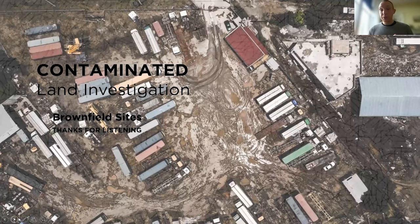So the first thing that we'll do during the phase 1 report is identify potential sources in the area. So the house that I showed you where there was an explosion, the landfill for that was several hundred meters away. A contaminated land consultant would have picked that up. Unfortunately, if we are looking at a single development, contaminated land consultants are restricted to testing within the site boundaries unless there are exceptional circumstances.